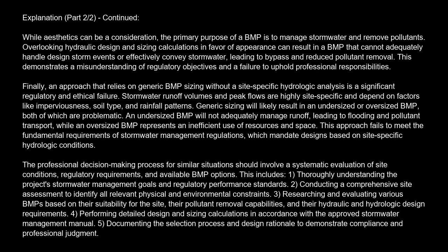Finally, an approach that relies on generic BMP sizing without a site-specific hydrologic analysis is a significant regulatory and ethical failure. Stormwater runoff volumes and peak flows are highly site-specific and depend on factors like imperviousness, soil type, and rainfall patterns. Generic sizing will likely result in an undersized or oversized BMP, both of which are problematic.